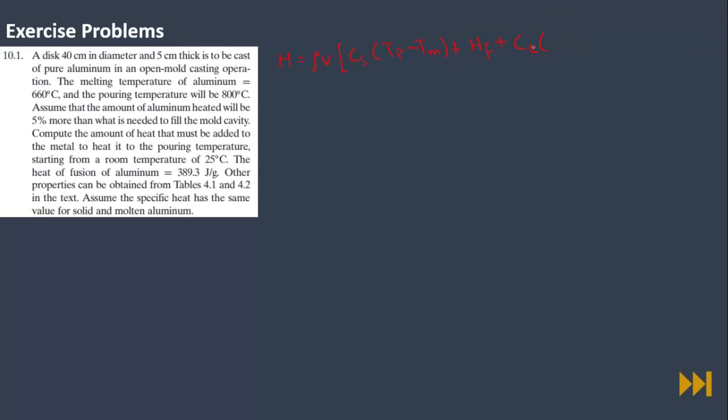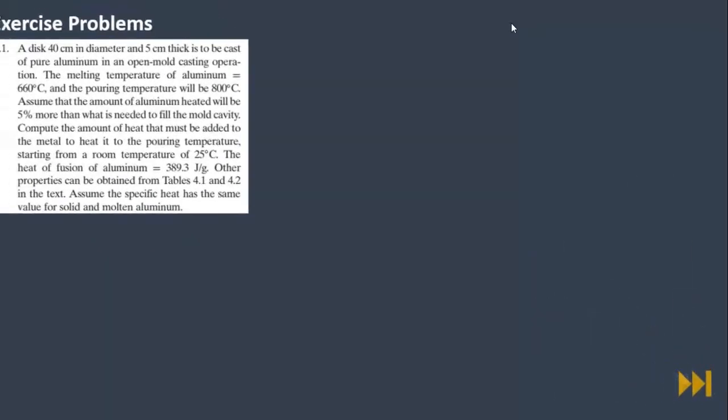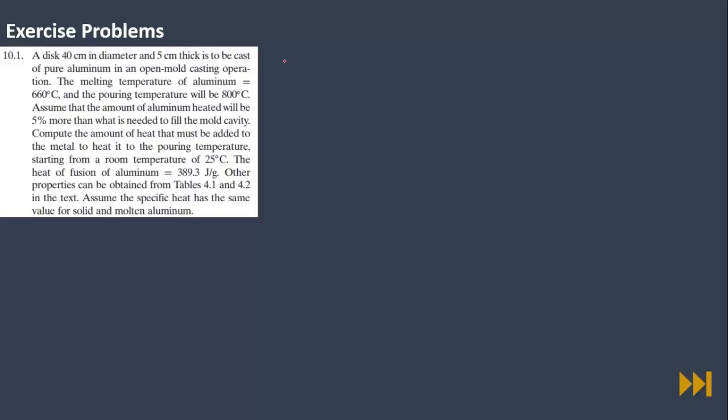Sorry, so if you remember the formula, that was equal to density times the volume times specific heat in the solid state times the temperature difference between the melting temperature and room temperature, plus heat of fusion, plus specific heat in the liquid state times the difference between the pouring temperature and the melting temperature.